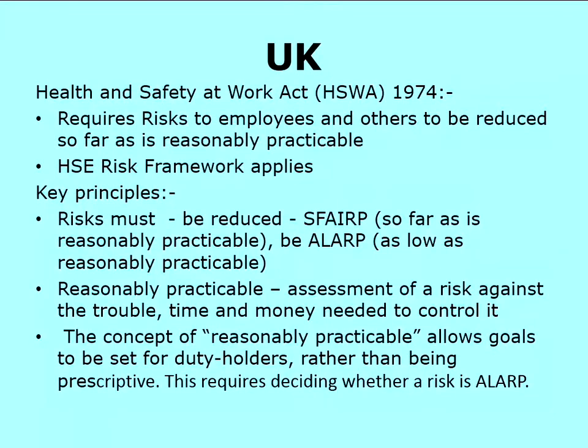There's a fairly good, consistent agreement of them internationally. And essentially, what it means is that ideally you want your risk to be low enough so that it's broadly acceptable and you're safe to operate. However, once you start quantifying risk, you need actually to put a quantified level against that. And that means that the risk has got to be 1 times 10 to the minus 6 of a person becoming a fatality per year associated with the infrastructure you're talking about.